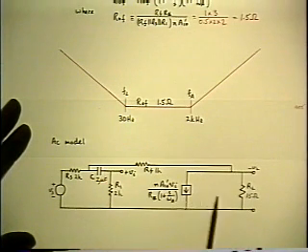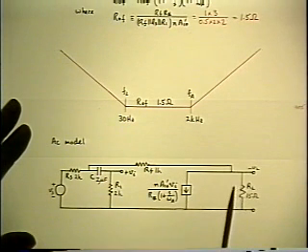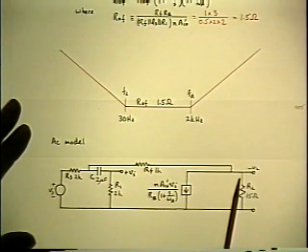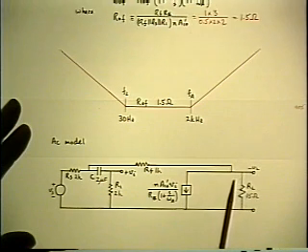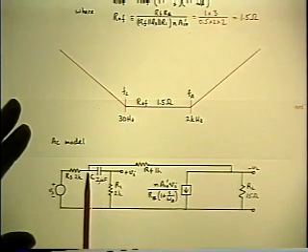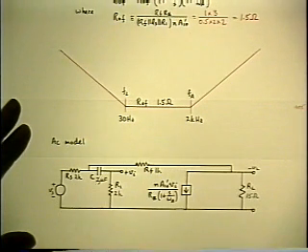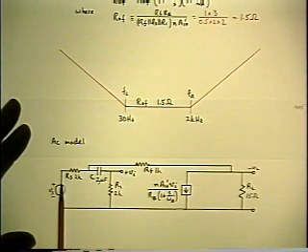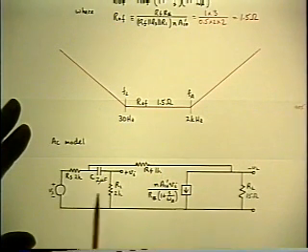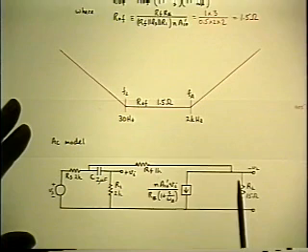That's why you get zero loop gain at infinite frequency as well. So once again, the only contribution to output impedance at infinite frequency would be the impedance of the feedback path itself, plus RS parallel R1, because the coupling cap would be a short, which would be 1K plus 2 parallel 2, or 2K. So the output impedance ought to be flat at 2K at infinite frequency.